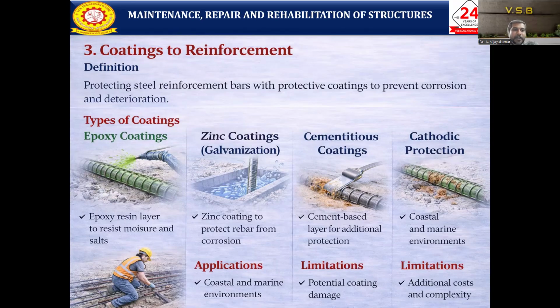Epoxy resin forms a layer to resist moisture and salt content, protecting the reinforcement. For zinc, we need to dip the steel reinforcement into zinc, and the zinc creates a layer on the steel reinforcement. This can be used in coastal and marine environments as a protective coating.